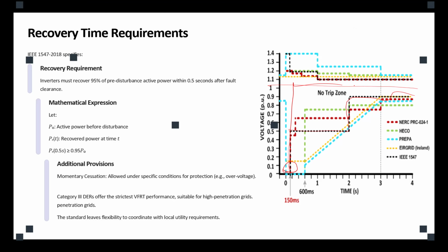Now, during the fault ride-through, we actively change the control or the protection threshold. So if we instantly went to the nominal voltage from before the fault, what protection sees is a huge overvoltage. So it's considered another fault and trips. We want to ease the DER into the steady state, into the system. Make sense?